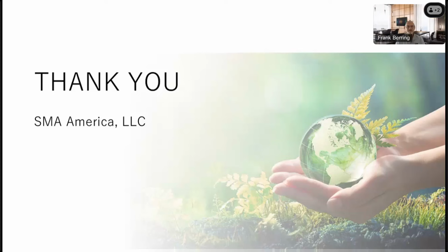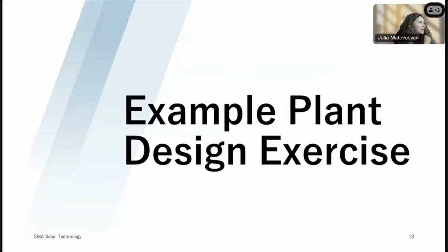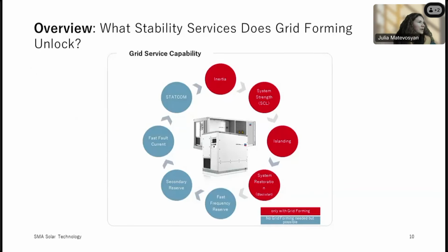Next one, on slide 10, how do synchronous grid forming enhance the system strengths of the grid? Are you measuring that using short circuit level only or some other behavior as well? It's a good one. Typically, yeah, we've had that discussion before, haven't we? Typically, the short circuit level is considered the proxy to system strength, but at the same time, that very quick propping up of voltage does contribute to system strength. So I think the proxy of short circuit current is the most common reflection of system strength and in discussion in the industry today, though.